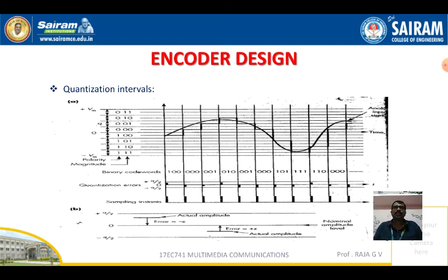To represent the digital form of the amplitude of a set of analog samples would require an infinite number of binary digits. When a finite number of digits are used, each sample can be represented by a corresponding number of discrete levels. The effect of using a finite number of bits can be seen here. So this results in 4 positive and 4 negative quantization intervals.